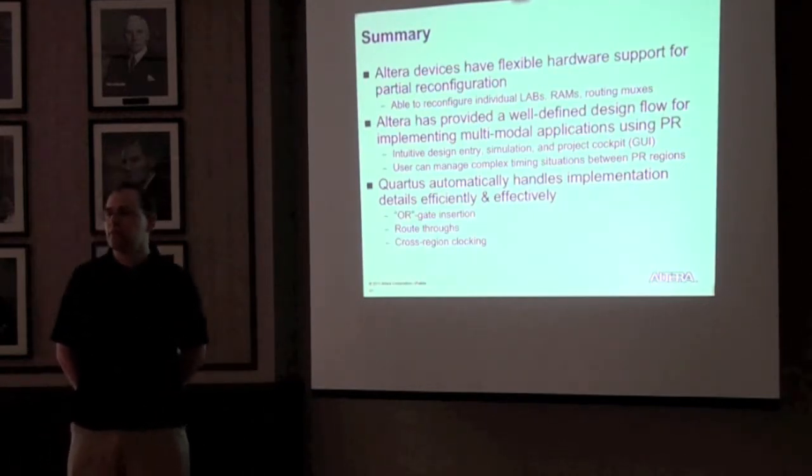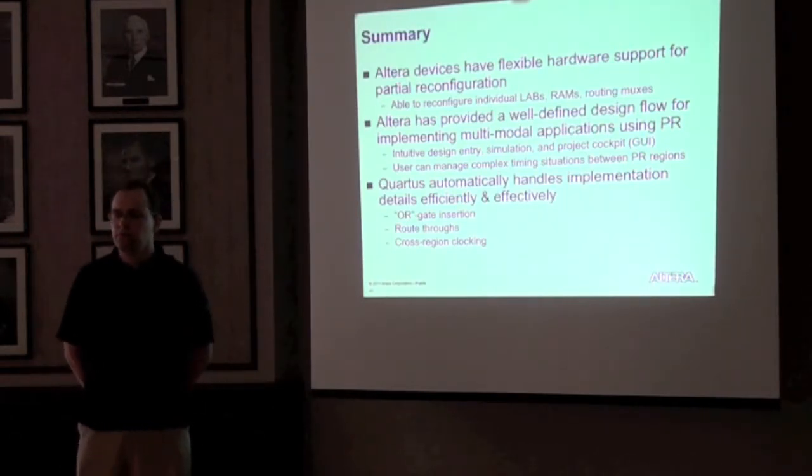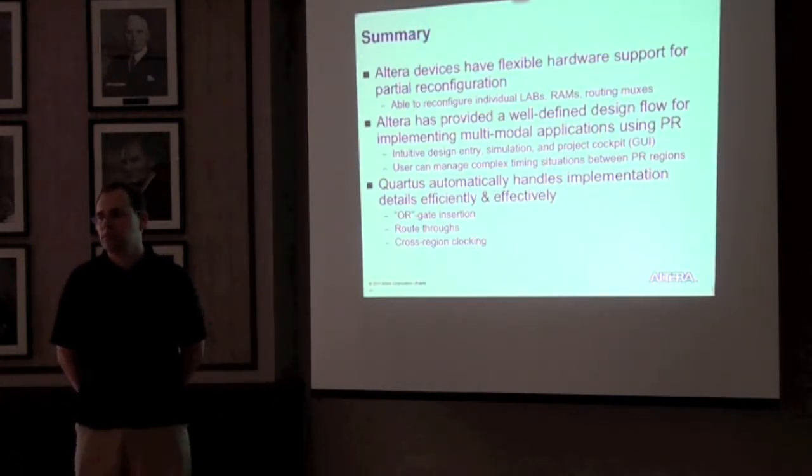Is it possible to disable the route repeatability? The reason I ask is because you were talking about lots of small PR regions, and I know one of the researchers here, I don't see him here right now, but he was always asking designer folks, what happens if I have the same design over and over again in different regions of the chip? And the answer is the same design, so you have to recompile it every single time. Here, there seems to be an additional difficulty that if you're doing a route across that region, then that becomes even more specific.